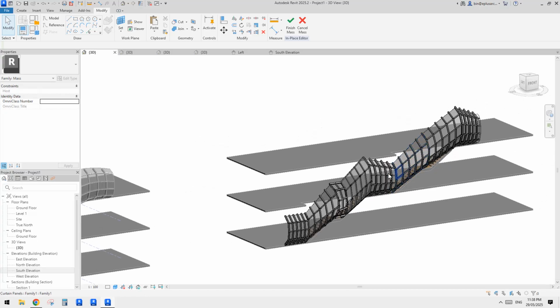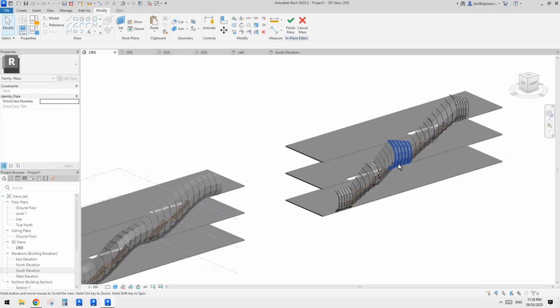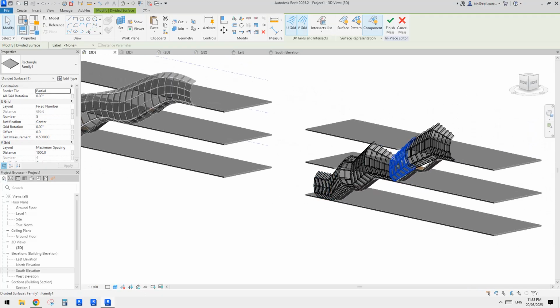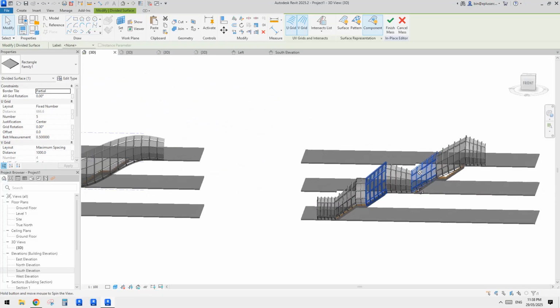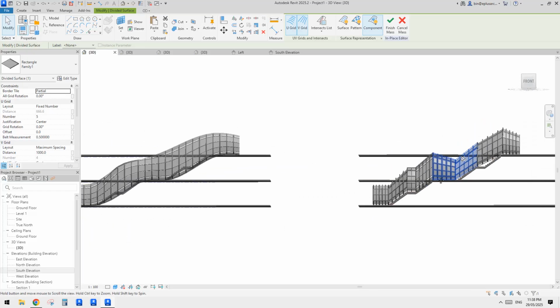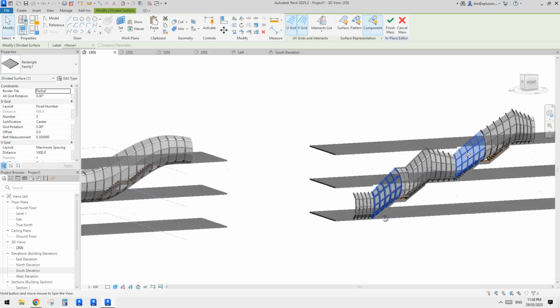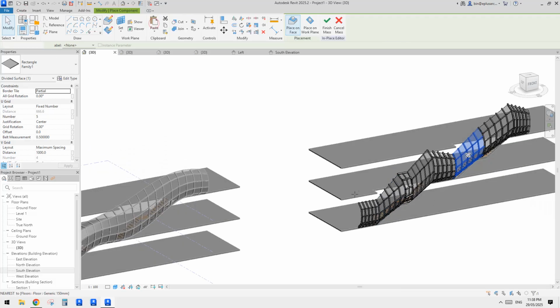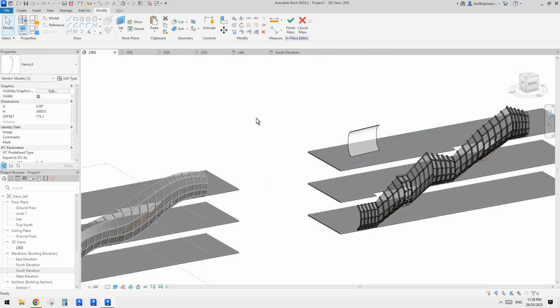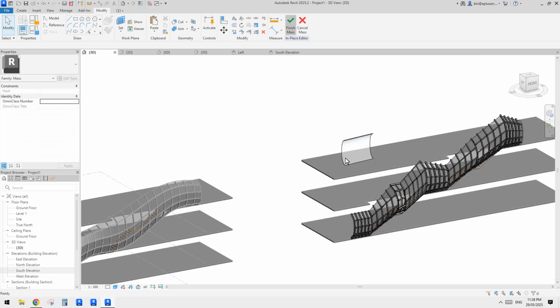So I'll leave it here because it's a bit long already. So basically this is the method I think we can use as well. So if you want to create this type of shape, we can just create an adaptive, always vertical profile, and then we use this to create form. Okay, so yeah, so this is it.